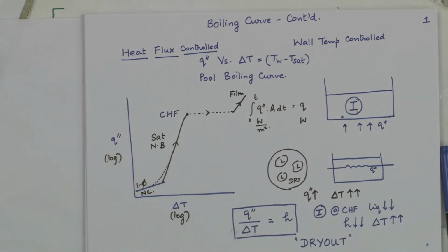Okay. So, CHF is kind of a misnomer, but it has been conventionally used and we will not change the terminology that much. But you must understand that it has nothing to do with the heat flux per se, it represents the situation where the heat transfer coefficient suddenly degrades.